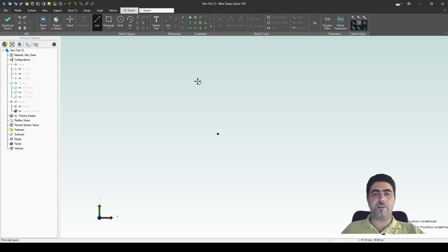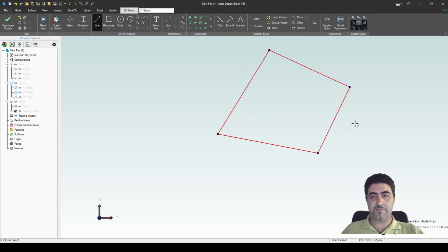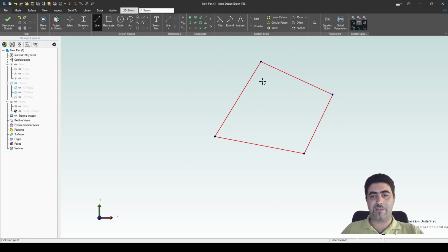So let's start by trying to make a square, right? In parametric CAD, it is generally advisable to start designing as far away from the actual shape that you want to achieve, and then constrain it and dimension it so that you get what you need. Once you build up experience, you can start with something that's closer to your final desired result. But this is a good rule of thumb as you're still learning. So let's say that we want to make a square. Okay,